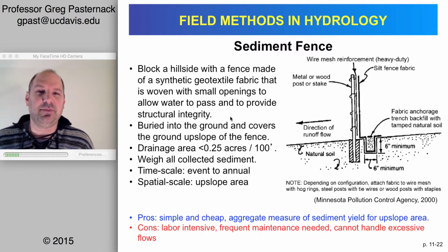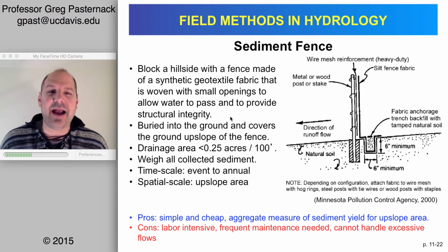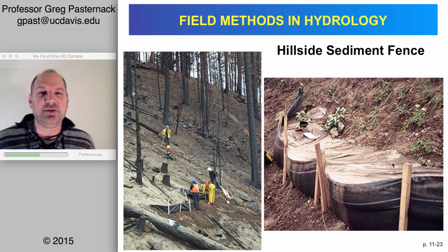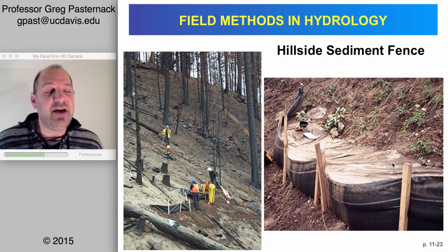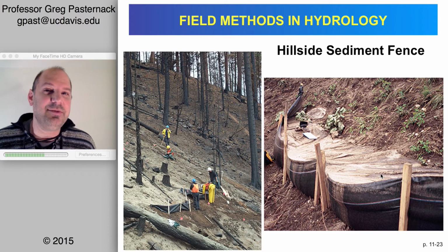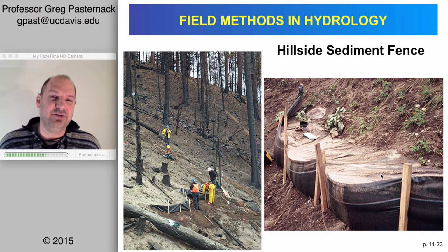The biggest challenge with this approach is just the sheer labor intensity of it. This is just like backbreaking work when you have this much sediment. So of course, the more often you go in and collect the material, then the less work it's going to be each time. But with a big enough event, you need to dig out all this material, assess the volume, and then at a minimum, take a representative sample for bulk density so that you can convert from volume to weight. Or you have to dig the whole thing out and just weigh the whole thing. And this is really just very difficult work to do.